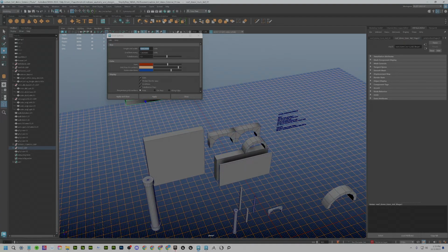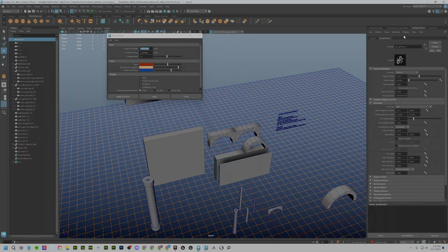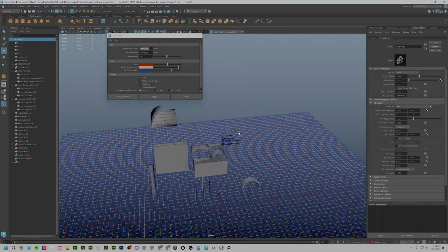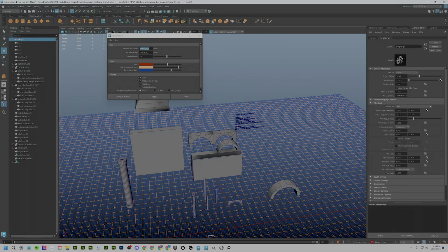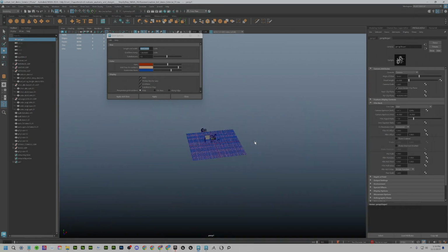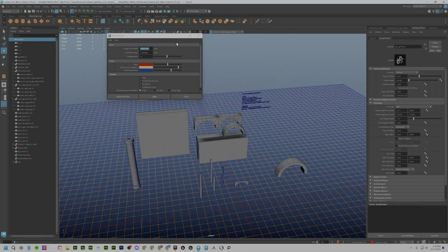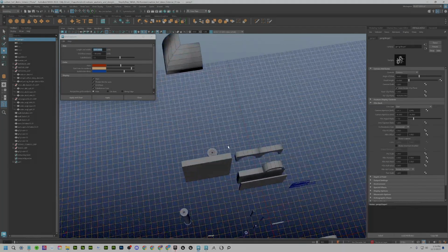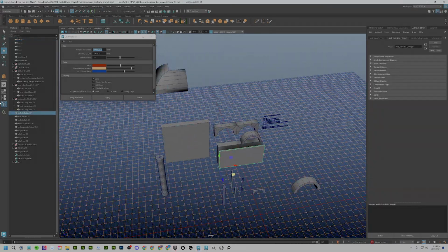So yeah, go to your perspective camera in your outliner, go to the perspective camera shape 1 camera attributes, and change the near clip plane from, I think it's 0.1, to 3 or 4. I think some tutorial or resource said make it 3, but I don't see any more flickering now when I'm working. If you want to do a great big building or tower, now you can. And then the far clip plane, I just add a couple zeros in there, and now I can zoom all the way out. Now I can build my city without having horrible artifacts and flickering and objects appearing and disappearing. So that was really great to find out today.